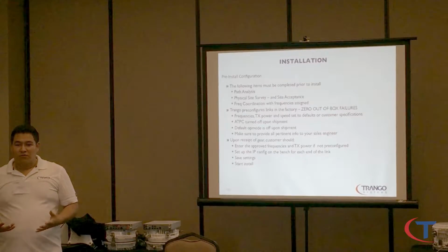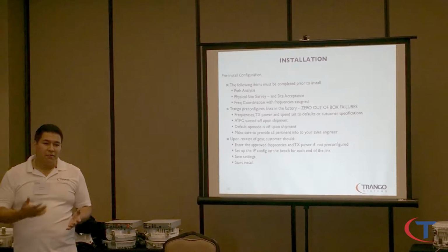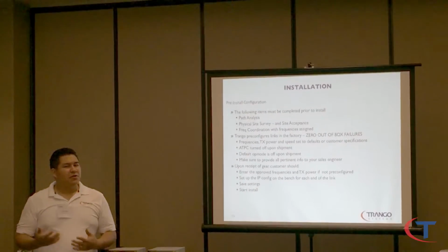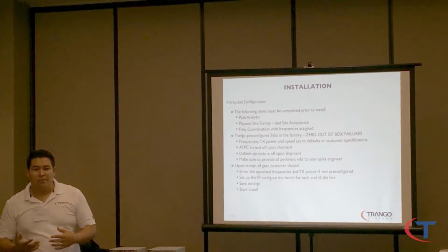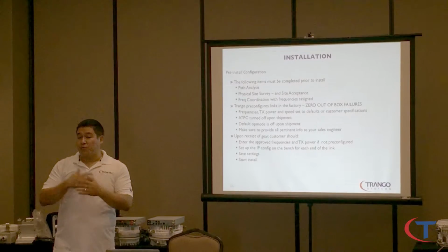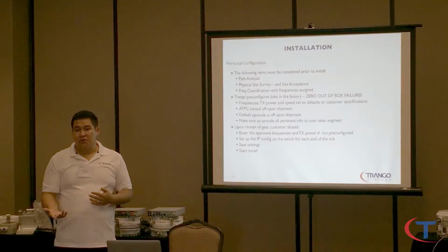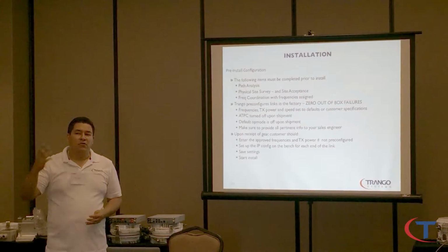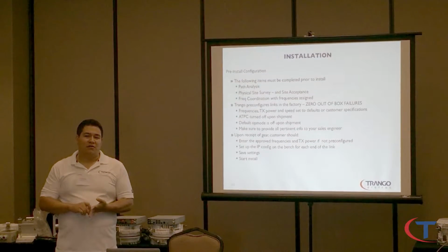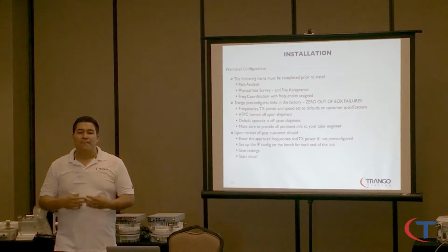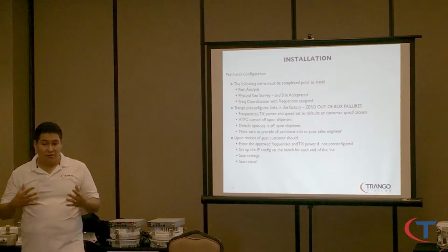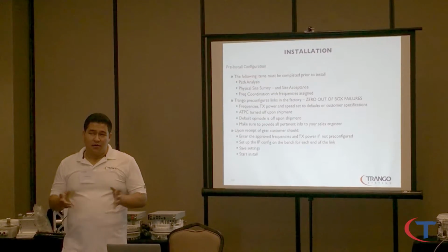Site acceptance. If you're going to lease, you want the best thing because you're going to pay for it. Typically, it's going to be out there, American Tower, big infrastructure. If you go onto a private tower on the back of a hill, on top of somebody's house, or on the hospital building, make sure they have proper grounding lugs outside and the rack space you need.